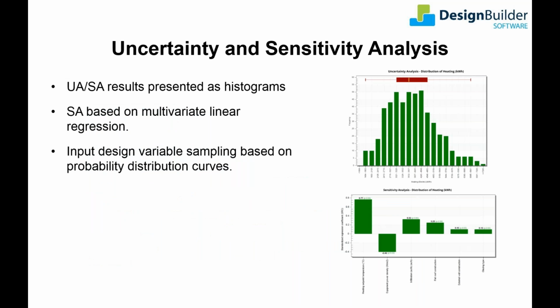Very briefly discuss the uncertainty and sensitivity analysis tools as we're planning a webinar dedicated to this topic in the weeks ahead. For those of you unfamiliar with uncertainty and sensitivity analysis, uncertainty analysis reports confidence levels in simulation outputs based on uncertainties in specific inputs. Sensitivity analysis reports on the design variables having the greatest impact on your key simulation results.